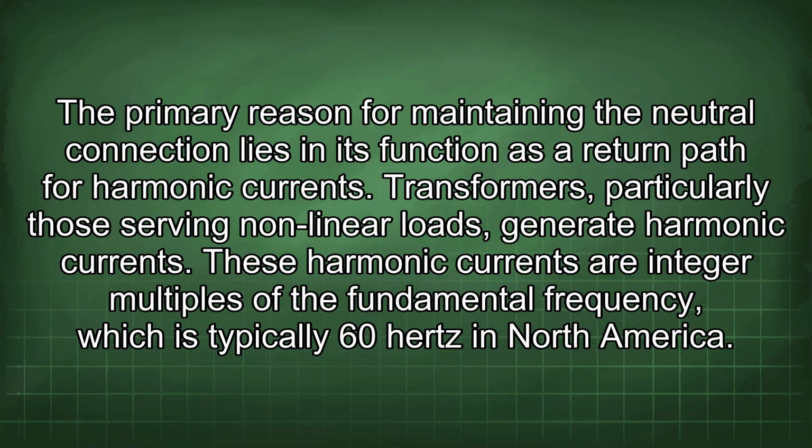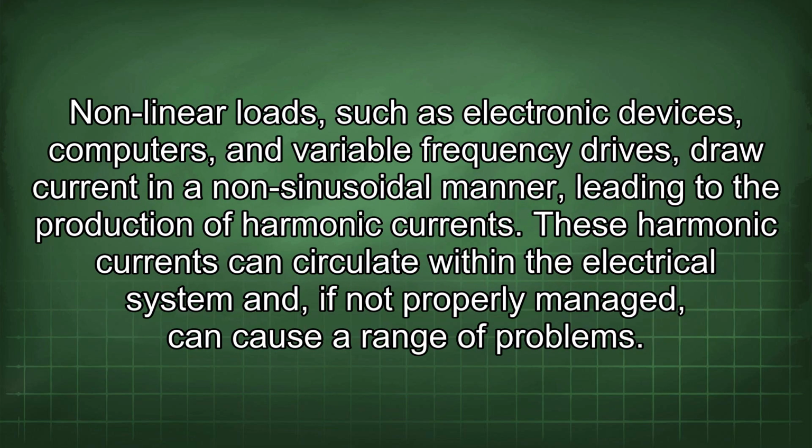Transformers, particularly those serving nonlinear loads, generate harmonic currents. These harmonic currents are integer multiples of the fundamental frequency, which is typically 60 Hz in North America. Nonlinear loads, such as electronic devices, computers, and variable frequency drives, draw current in a non-sinusoidal manner, leading to the production of harmonic currents. These harmonic currents can circulate within the electrical system and, if not properly managed, can cause